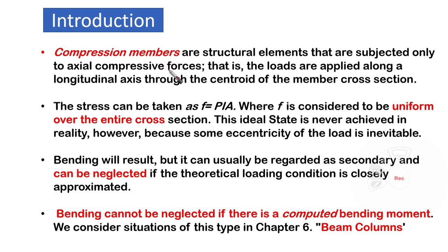That's an important issue: compression members here means pure axial compressive forces, because we are going to deal with another type of element titled beam column elements, where the element is receiving compressive forces, and in addition there are flexural straining actions or moments that are going to develop and be resisted by this beam column.